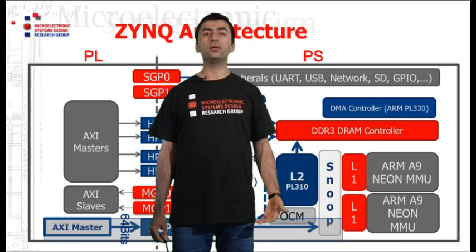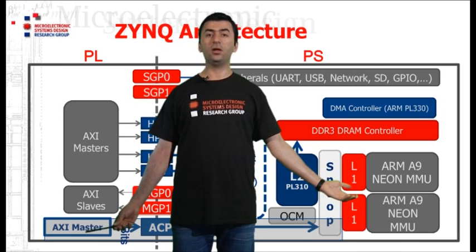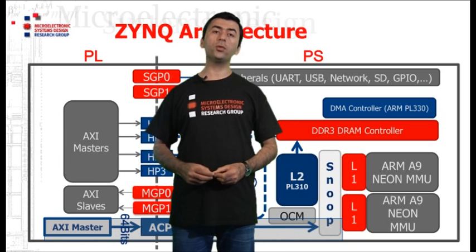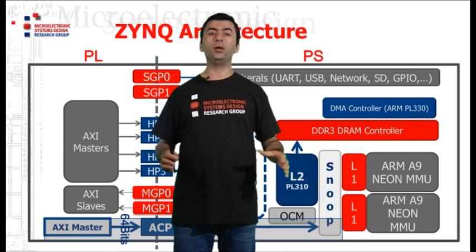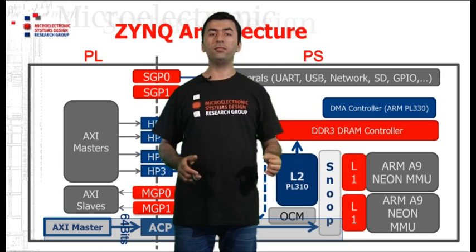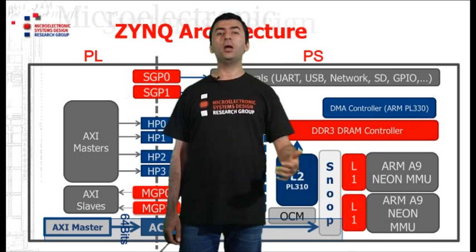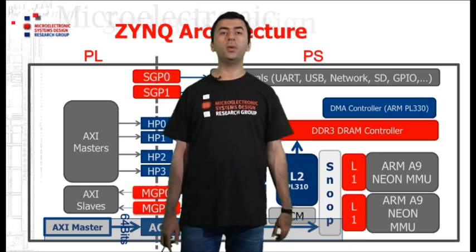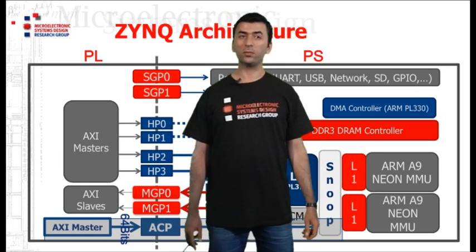This allows the ARM host and the accelerator to share data very fast with low energy consumption. But as I will show you in future videos, if you don't design your structure, your algorithm and memory allocation very well, then this may not only fail to improve your performance, it can in fact increase runtime and increase energy consumption.